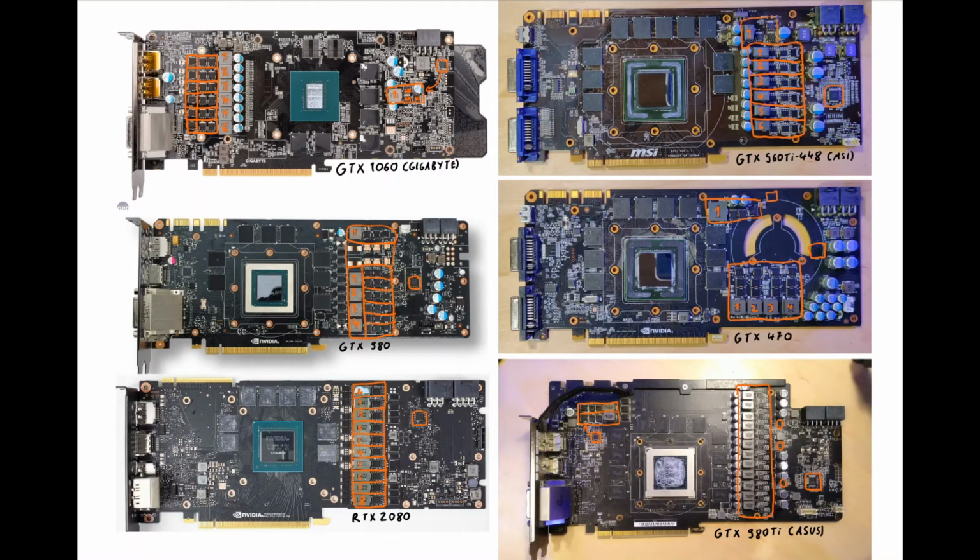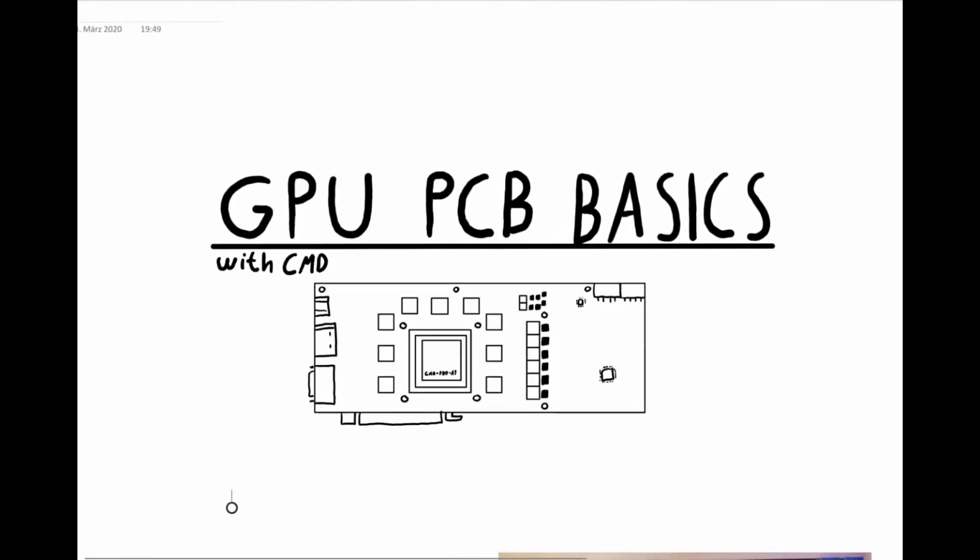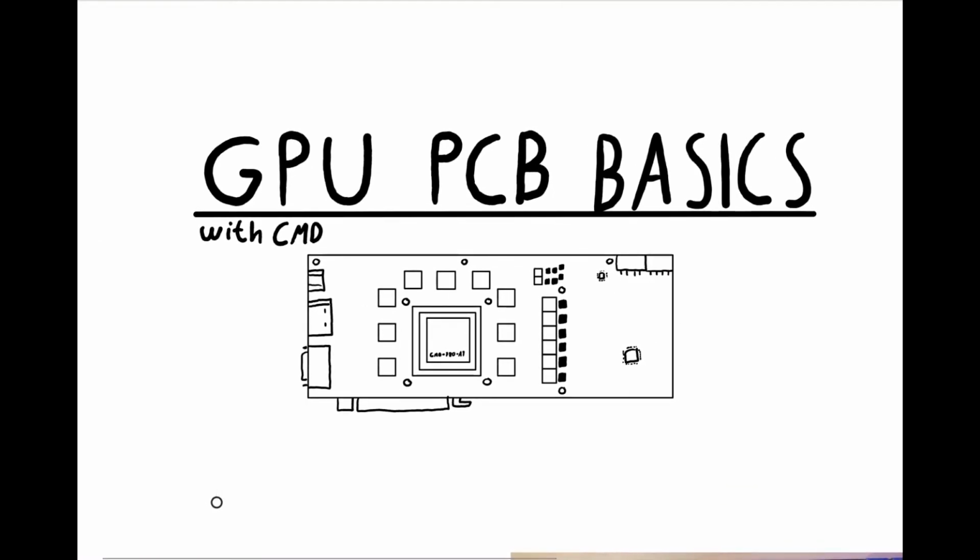And then for MOSFETs, obviously, for the low sides, more current capability is of course better, and lower RDS(on) resistance is better. That also goes for the high sides, but the high sides do not have to handle as much current. So high sides will pretty much always have higher RDS(on) and less current capability, because they are high sides. You don't need as much on there. So, but yeah, that should be it for GPU PCB basics.